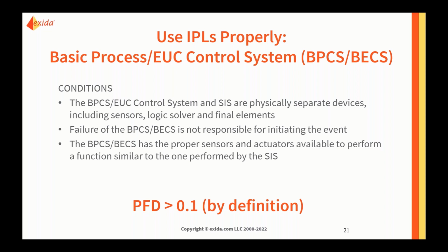Similarly, if this is our initiating event, we will find that same limit of credit that we can take at the single failure in 100,000 hours, or roughly one failure in 11.5 years or so. So our basic control system is going to be limited by those SIL definitions unless we meet the individual SIL requirements in our design or our prior use of that control system.